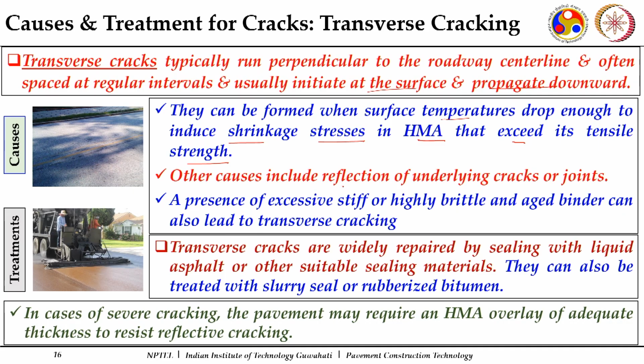Other cases may be, say, if extensive cracks are there in the transverse direction in the underlying layer, then also it may get reflected, or it may get transverse cracks because of the action along those cracks.